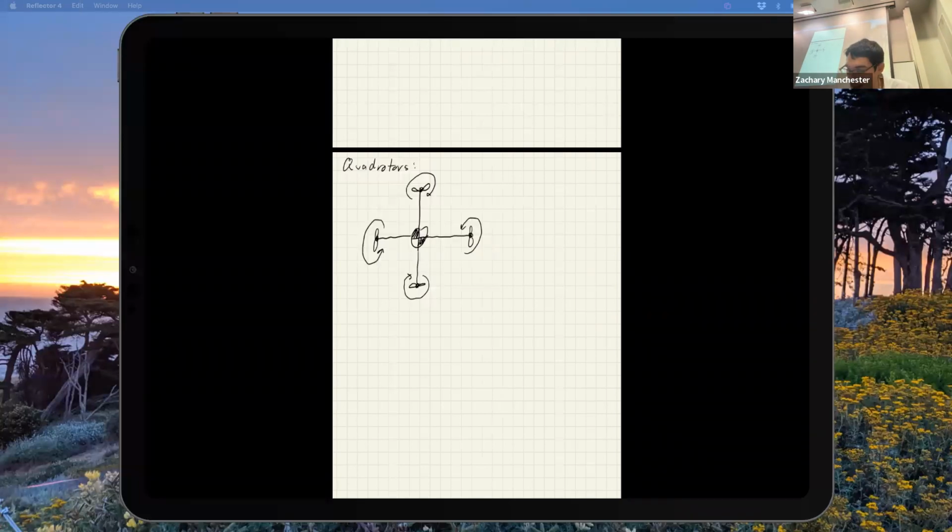And then we're going to have mass M, inertia J for the whole thing. And then we'll call these little vectors from the CG to each propeller s_i. And this will be in the body frame, I guess. All depends. So you'll have four S's, and this accounts for whatever the vector is. So it'll be super generic.